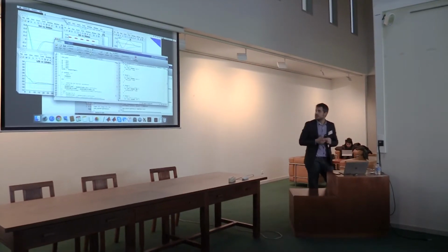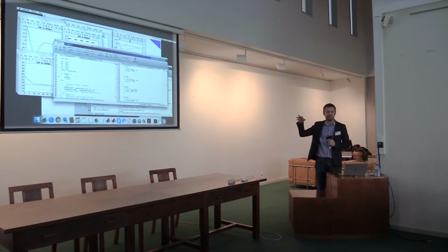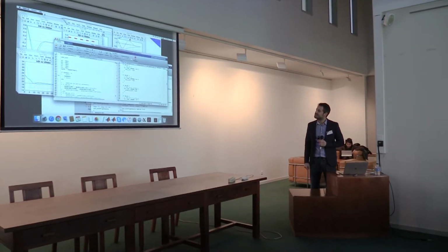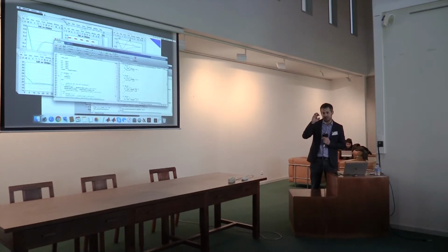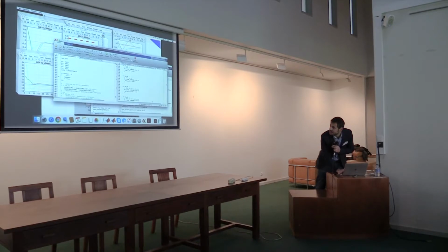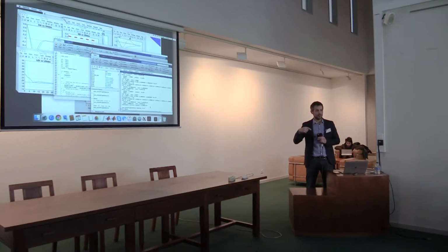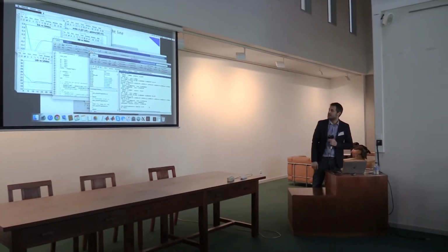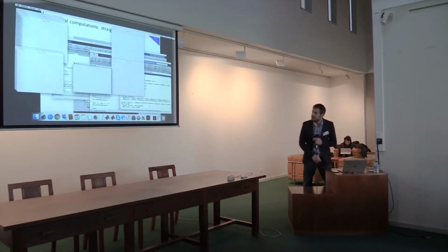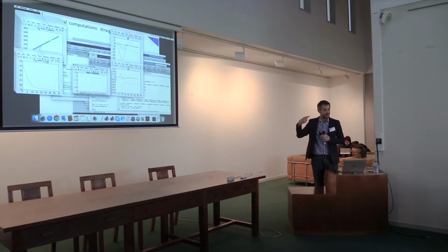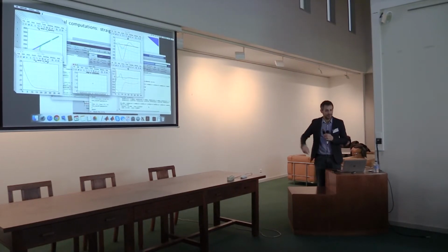And actually, this is just the first step. Since we have some state and input constraints here, in order to include the constraints in the optimization process, you are using a barrier functional trick. So you're including the constraints in the cost functional. When we find a minimum, we update the parameters of our barrier functional and run it again. We use as initial trajectory the optimal trajectory at the previous step. So this is the iterative process. It's like a continuation method, okay?